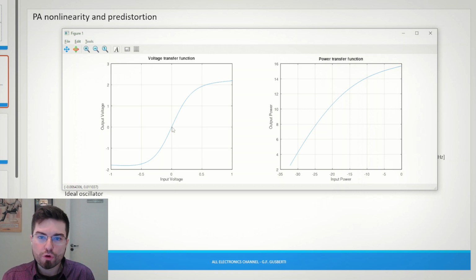As the input voltage of the amplifier increases, we begin to saturate the amplifier, and as we try to excite the amplifier more and more, the output of the amplifier will not respond because we are saturating the amplifier, we are approaching the limits of the amplifier. This region here is called the large signal region, because for these regions here and here, we excite the amplifier with such a strong signal that it runs to its limits and the linear assumption is broken.